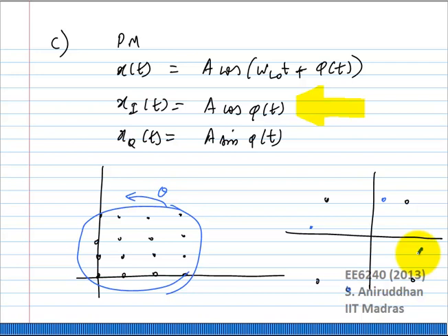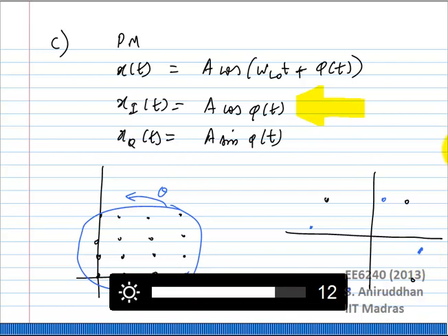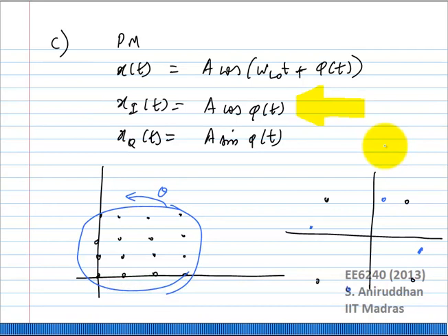Now you have to preserve each of these subcarriers very, very carefully. If you have any mixing between these subcarriers, it will completely destroy your data rate. Obviously, when you say orthogonal frequency division multiplexing, you expect the subcarriers to be orthogonal to each other. If they are not, you have a problem.